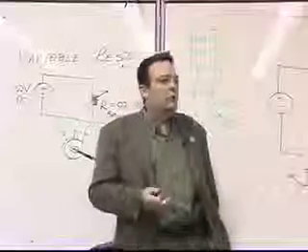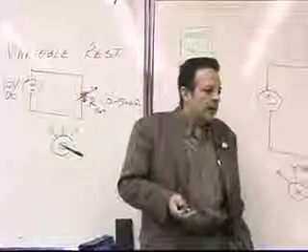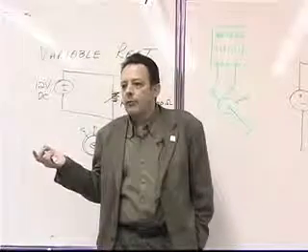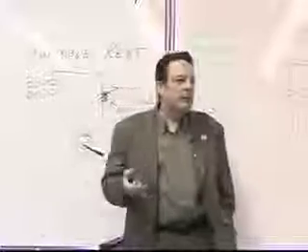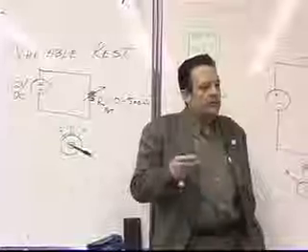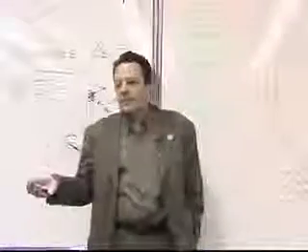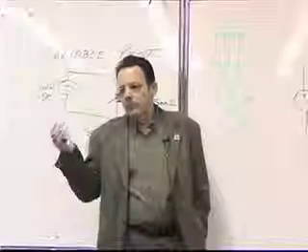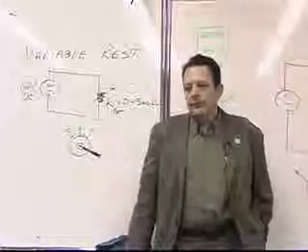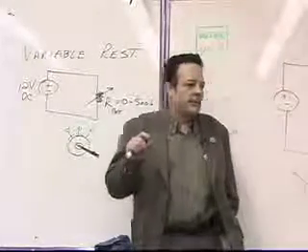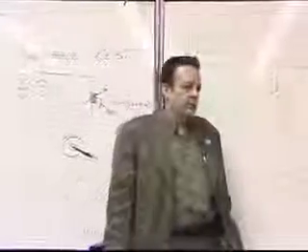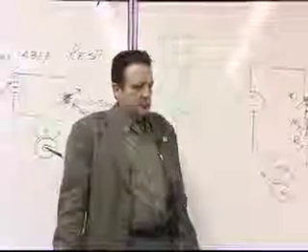So generally, you will not find rheostats that are rated at very small power ratings, like half a watt. You're generally not going to find rheostats that are rated for 0.5 watts. On the same hand, you're not going to find potentiometers that are rated for 5,000 watts. If you're looking for some kind of a variable resistor that's rated for 5,000 watts, you're almost always going to see that described as a rheostat, not a potentiometer. Okay? But really the function of it is not much different.